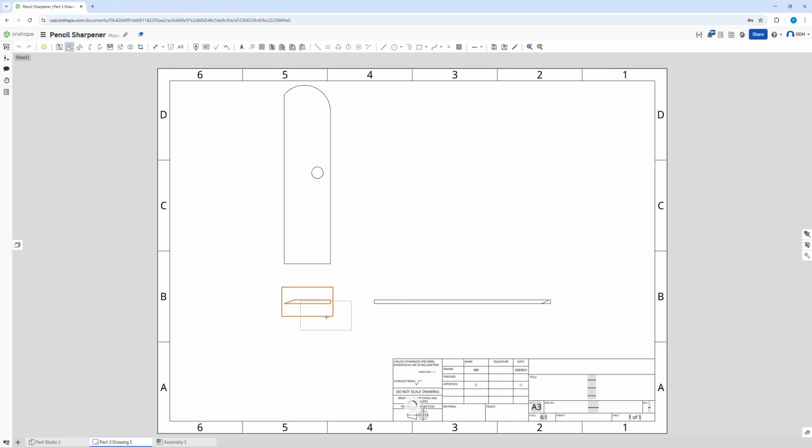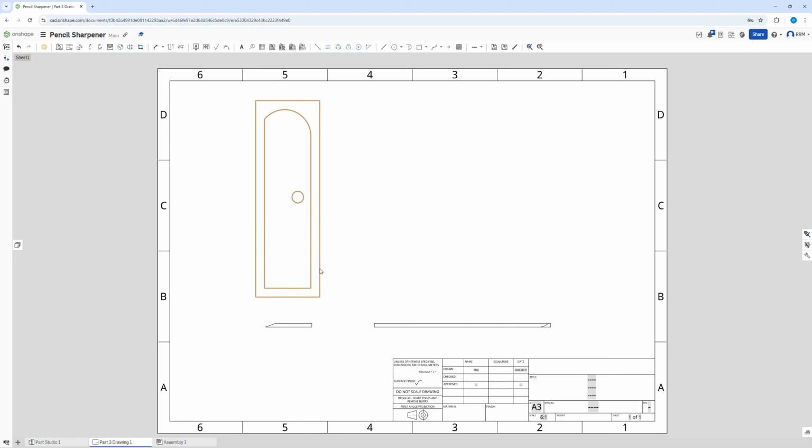You have your drawing set up, you can move things around. So you keep on projector view and you can project more parts, but we don't need to do that. We've got 3 views, which will be enough. So by moving the parent part, the others will change, as you can see. And you want them so they are relatively equally spaced and enough space around them for the dimensions. Now, once you're happy with that, you can go up and you can choose the dimension tool.